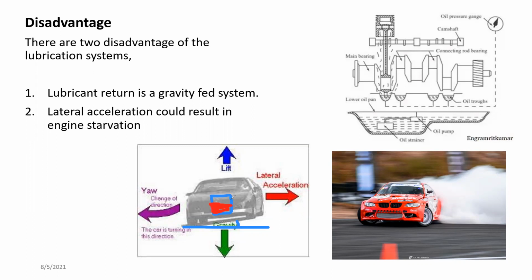So oil is actually sloshing from one side to the other, front to back, side to side, right? And these engine oil pans are not that deep. If the oil pans are deeper, they can manage it and won't have that much of a problem, because if it is deeper, the angle it needs to reach before the engine starts to be starved is higher.